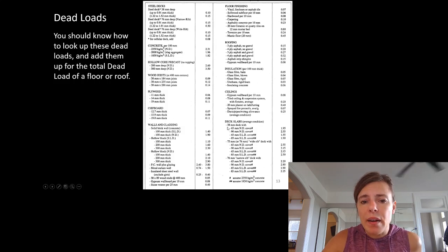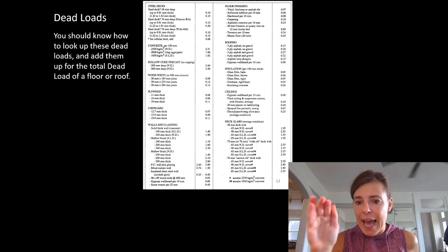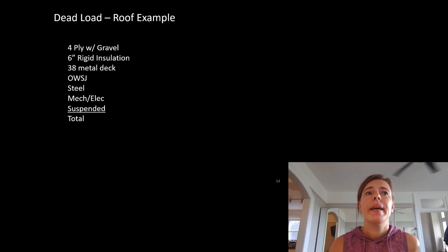But this one right here, 38 millimeter deck, 65 millimeter normal density concrete, that is going to be the one we use again and again, is 1.95 kPa.